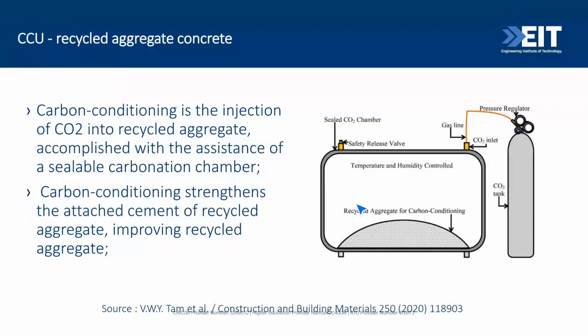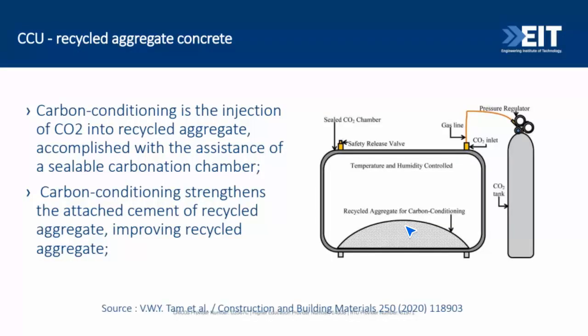This is retrieved from the literature as well, just to show you that you have the recycled aggregate in a sealed chamber and you can inject carbon dioxide. And this carbon dioxide, the carbon conditioning, will improve the recycled aggregate characteristics. And then you can use the aggregate. Nowadays, it's quite easy to observe in the recent publications that you can use recycled aggregate in both situations, structural concrete and also non-structural concrete.